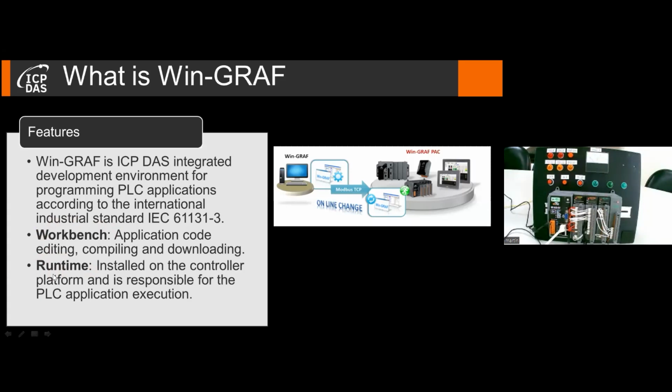So the runtime is necessary in order for the application to access the controller hardware, such as local IOs or memory, or access the communication interfaces for remote fieldbus communication. So the runtime is adapted to the controller hardware and is factory installed.